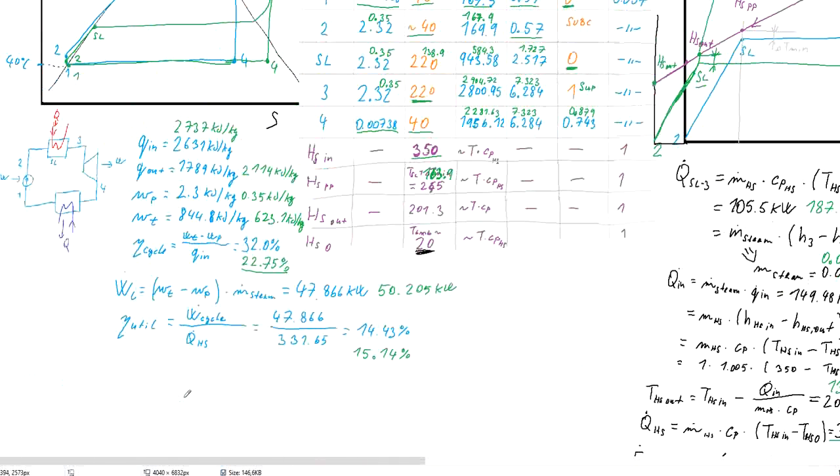And if we compare it with the steam cycle, here the utilization efficiency of low pressure steam cycle with superheating was about 15%, and if we had the expansion going directly from the saturated vapor line, it was even lower. Power output 50 kilowatt and less.